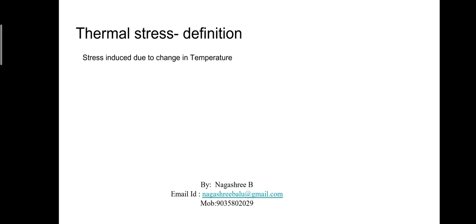But if the body is allowed to expand or contract freely, then there will not be any restraint condition developed. Therefore, no stresses will be set up whenever the body is allowed to expand or contract freely. So thermal stresses are the stresses induced in the body due to change in temperature, and whenever the body is allowed to contract or expand freely, there will not be any stresses developed in the body.